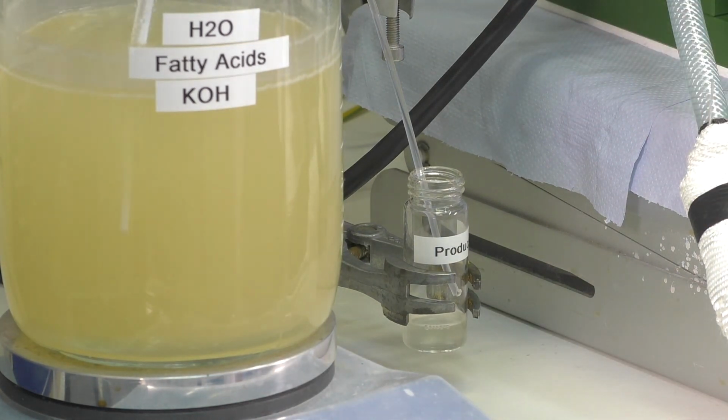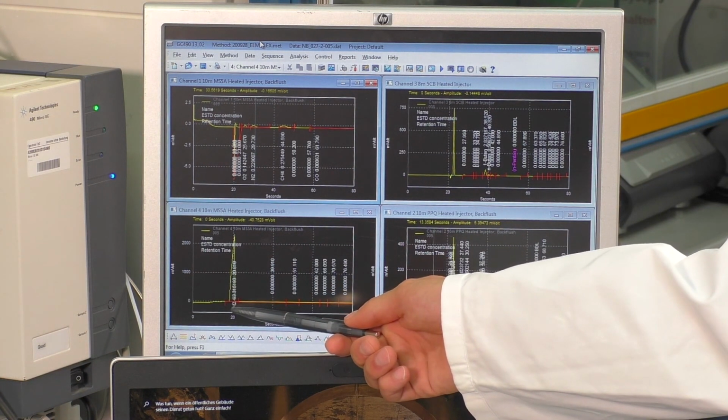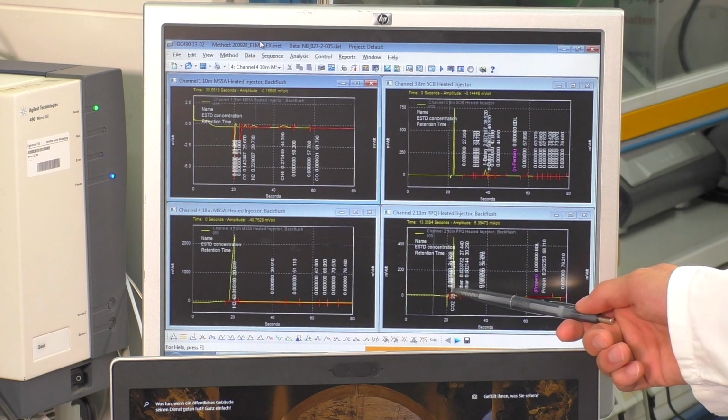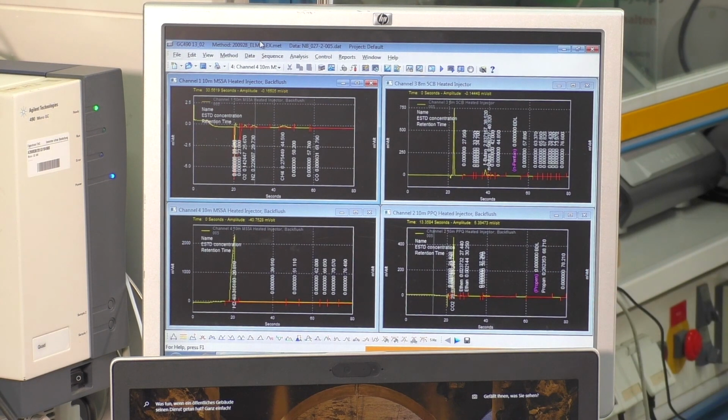and this can be analyzed, like I've said before, with a gas chromatograph. For the online analysis, like I've said, we use a process micro-GC 4-channel, where we can detect the gases, which in most cases are hydrogen from the counter reaction and carbon dioxide, which evolves due to the decarboxylation of the oxidized acid.